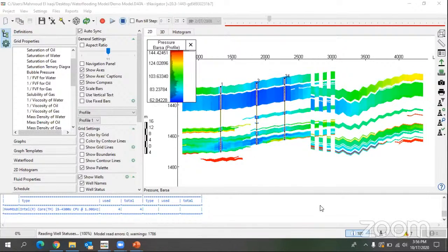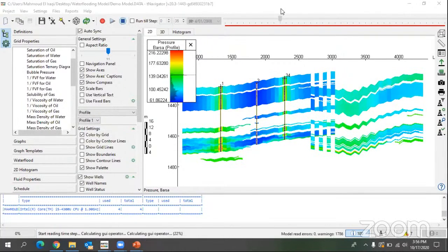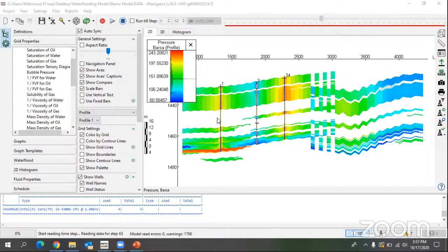So, for example, you can have polymer or surfactant that you inject with water on well one, and over time you need to see where this water is going, but you only trace this water. This is what we call a tracer, and we use it for surveillance for many reasons: to understand the permeability between injector and producer, the level of connectivity between injector and producer, and where the water is going. This is quite important. That's why I'm just explaining what a tracer means.